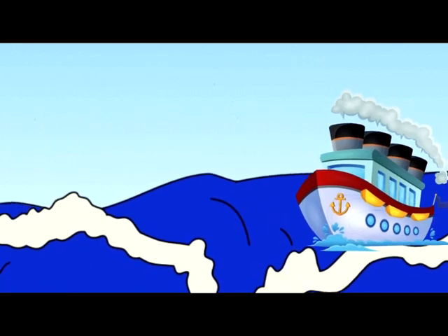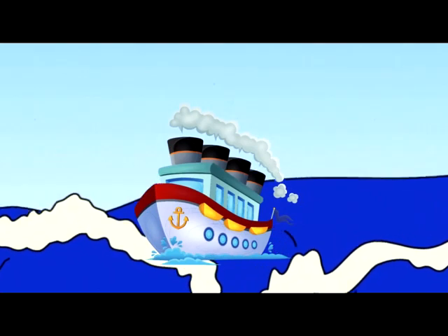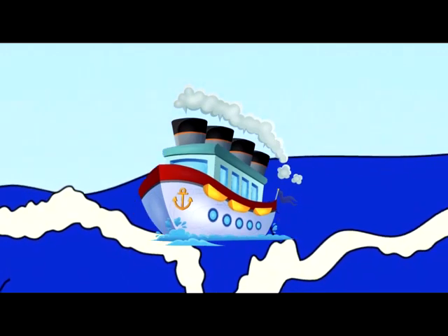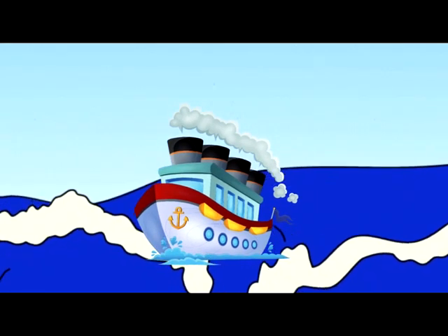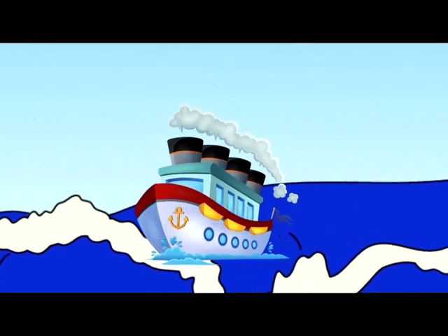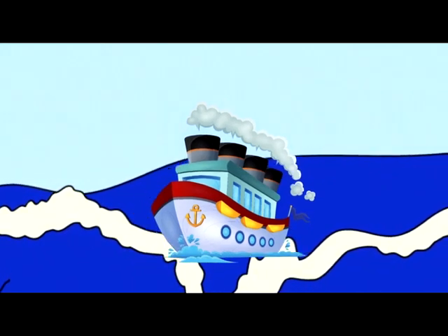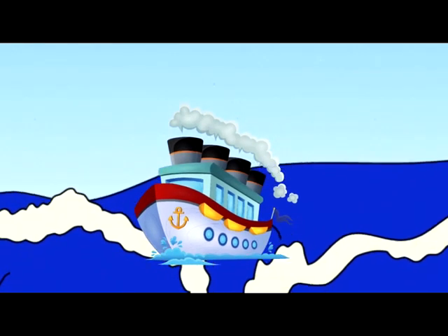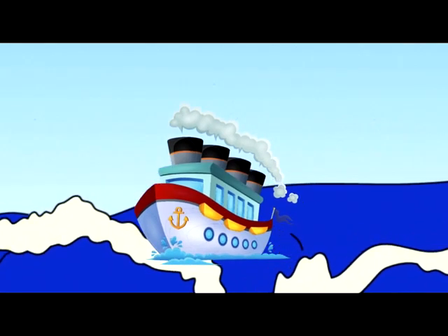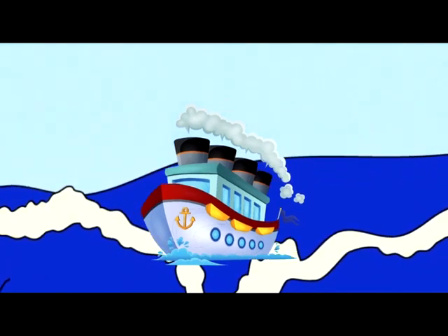Viscosity plays a significant role in ship design. Frictional resistance: as a ship moves through water, the water molecules closest to the hull adhere to it due to viscous forces. This creates a thin layer of water called the boundary layer that moves along with the ship. The friction between the moving ship and the stationary water in the boundary layer creates frictional resistance, which opposes the ship's forward motion. The viscosity of the water and the wetted surface area of the hull determine the magnitude of the frictional resistance.